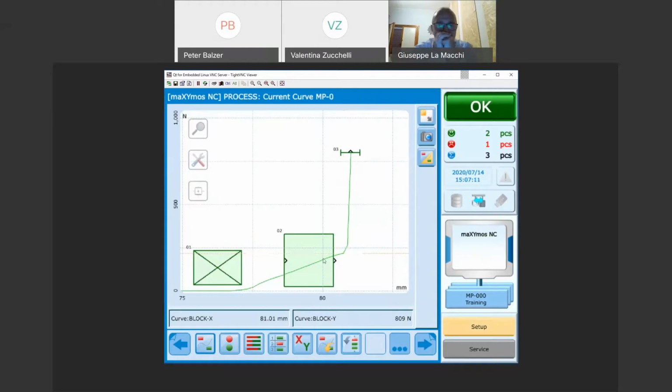But now it's also possible to go with that in this area. Instead of 5 millimeter per second, you can also go up to 30 millimeter per second. The only exception is, overall, our joining systems, if you have a process like this, if you go on a hard block, please do not exceed 10 millimeters per second. That's really important. But if you're just driving on a force with a linear increase, it's not a problem. You can also drive with 20 or 30 millimeters per second. That's okay. The only limitation is really just to avoid any damage on the mechanical part of the joining module.